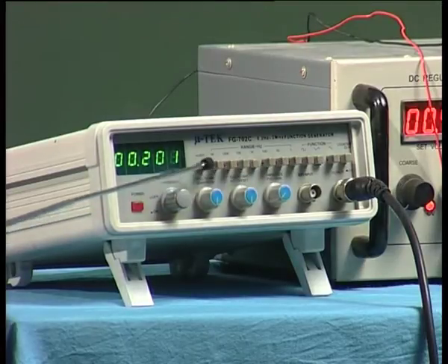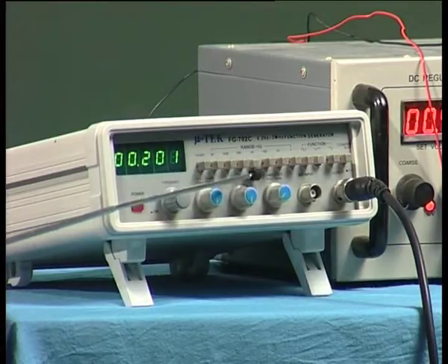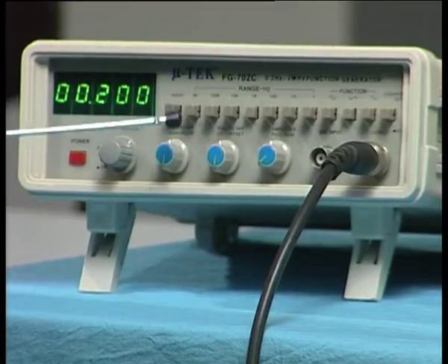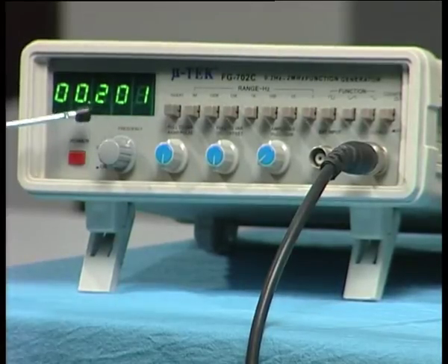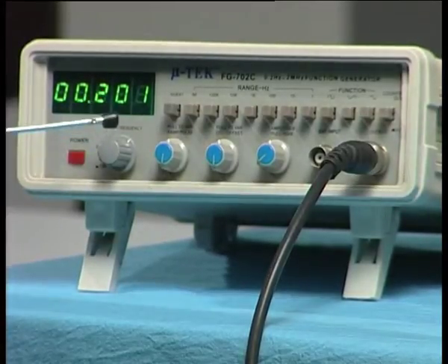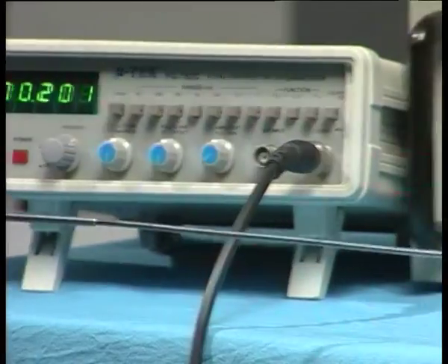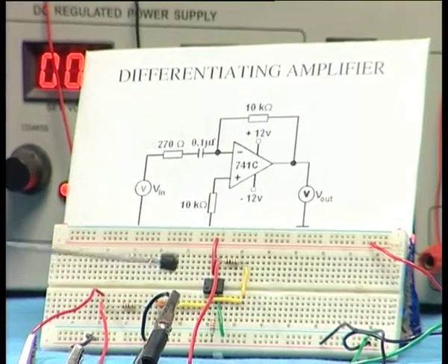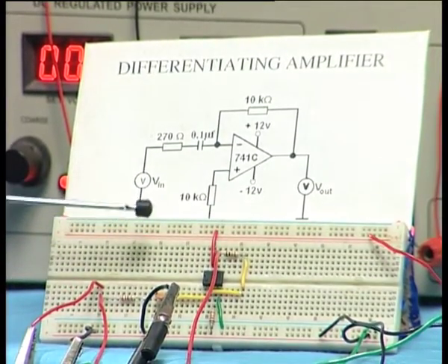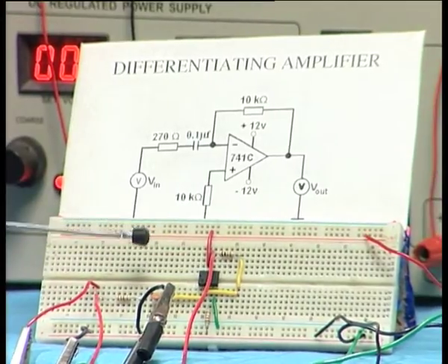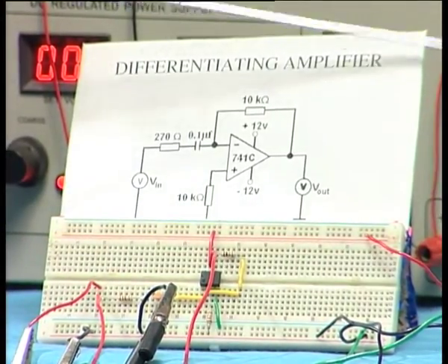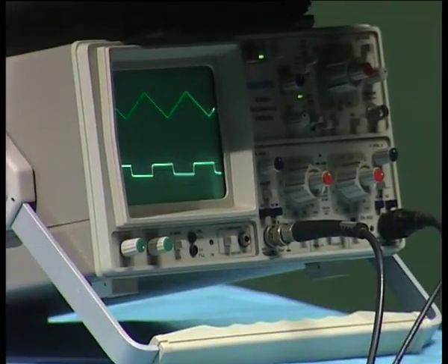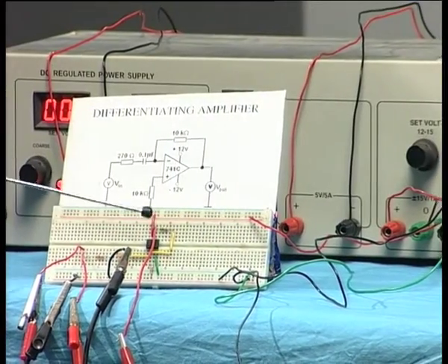All those outputs are there. These knobs are for applying different frequencies. I have right now applied 1 kilohertz. I have pressed this button, which corresponds to 1 kilohertz, and this measures the amplitude, which is about 200 millivolts. This is the input to this circuit. You have the same op amp, and the wiring is exactly similar to what I showed in the simulation. Now, this is a dual supply, and the plus and minus voltages are applied along the rail sockets, and then the output is monitored.